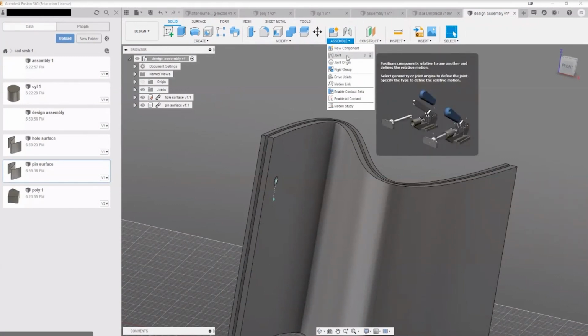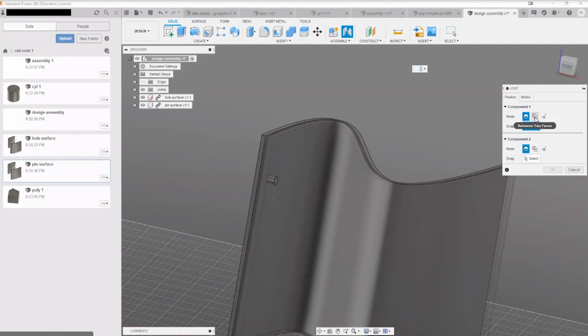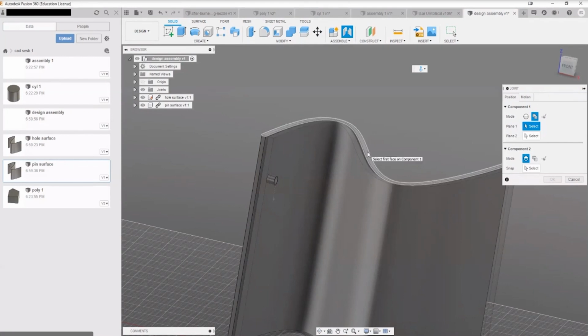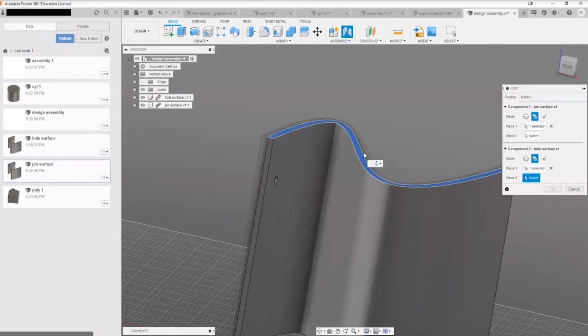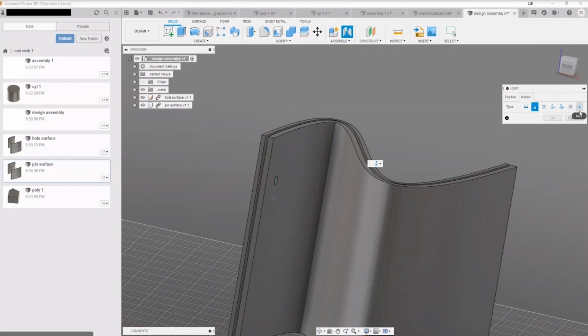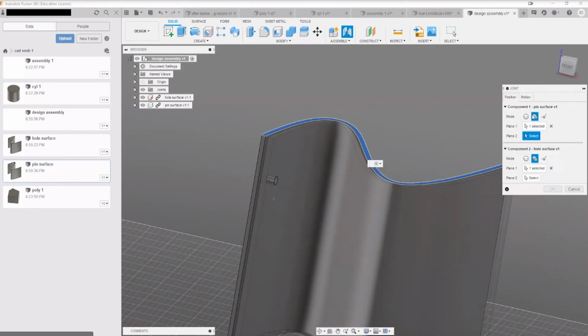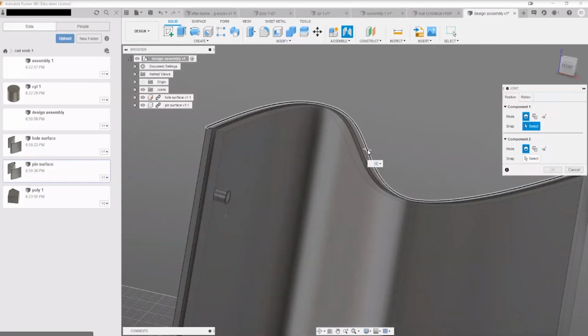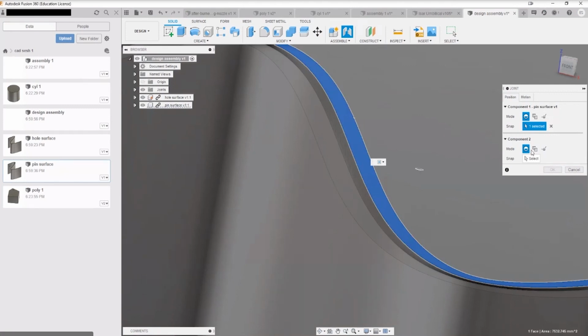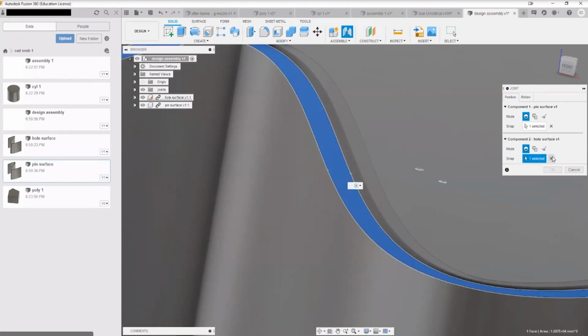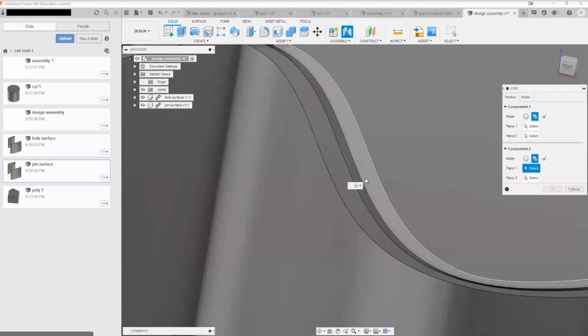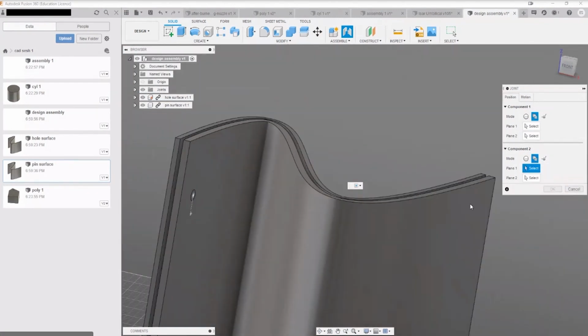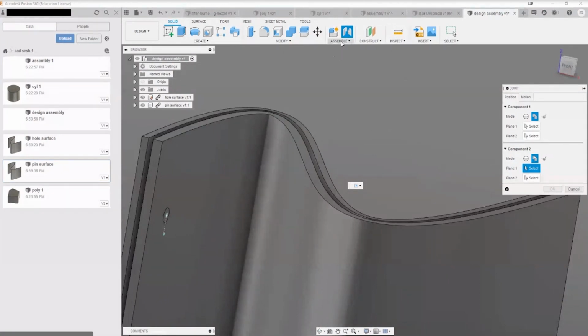So if I remember correctly, mode between 2 faces, I think you can select this plane and this plane. You can set them to be parallel. Okay, planar position. Okay, simple. So you know that this surface and this surface, yeah, there we go. They should be in parallel. All right. So see how you can set up a parallel joint as well.